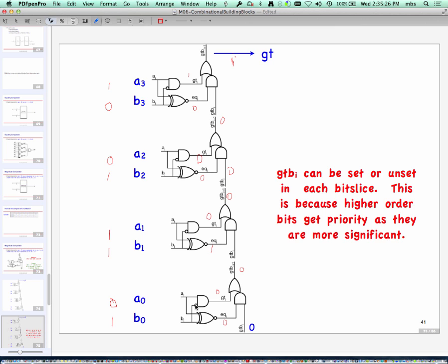In that case, I will have only 2 stages of logic, an AND stage and an OR stage, or I could map them using De Morgan's to a NAND followed by a NAND. In this case, I have to go through 4 stages of logic. So it's the usual trade-off that we have seen previously, which is I can have potentially fewer gates at the cost of a higher delay. In this case, my delay goes all the way like this. That's called the critical path.